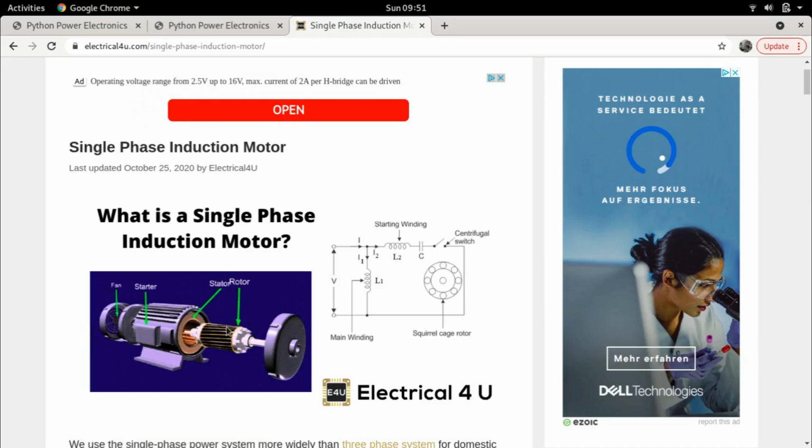Now if we take a look at this entire system, if we say the current flowing through the stator produces a flux which links with the rotor, and this flux path is our main path, then we need to determine the reluctance of this flux path.